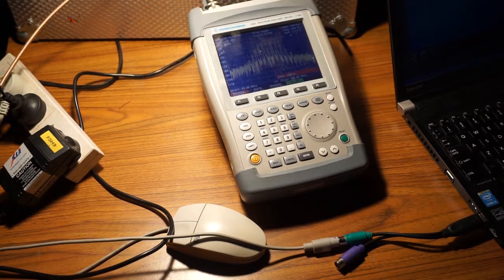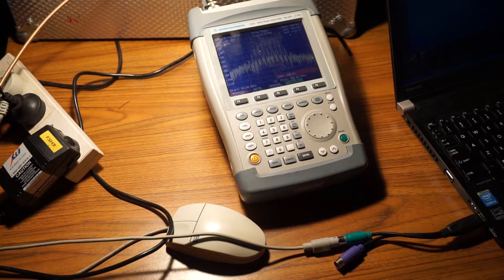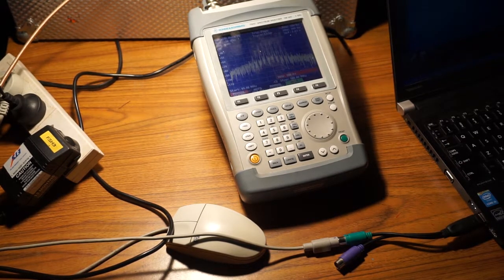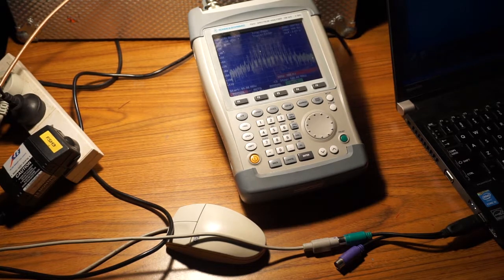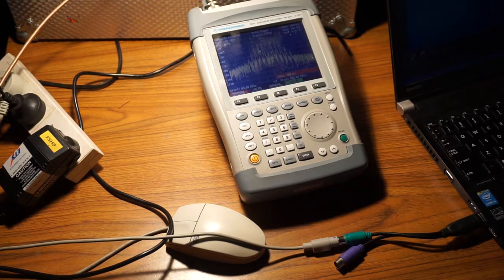By changing the modulation index, and I'll do it here, we can in fact change the carrier and make the carrier come up, make all those sidebands go away, just by very small changes in the modulation index. I'll just go back the other way, changing it slowly. If I could do it gently enough, you can make that carrier disappear altogether. So that's just about gone there. It's an interesting thing with FM.